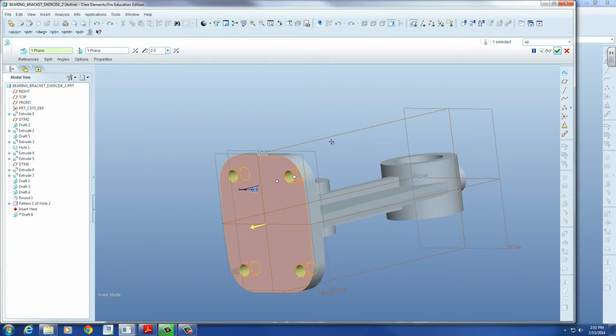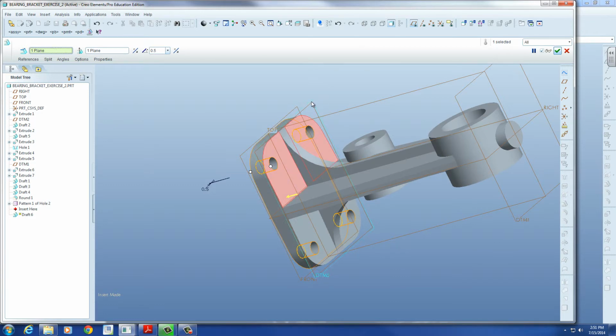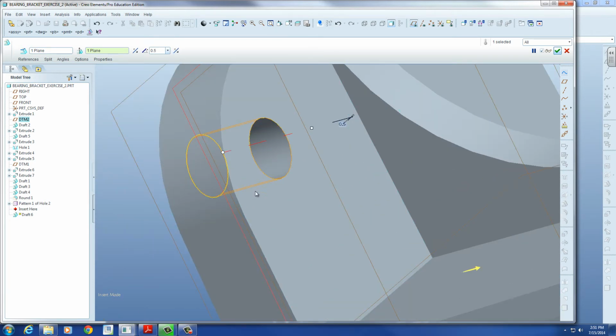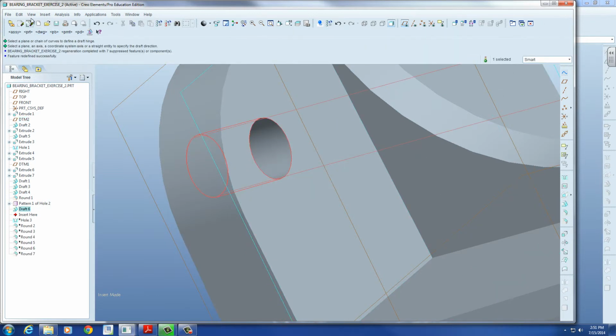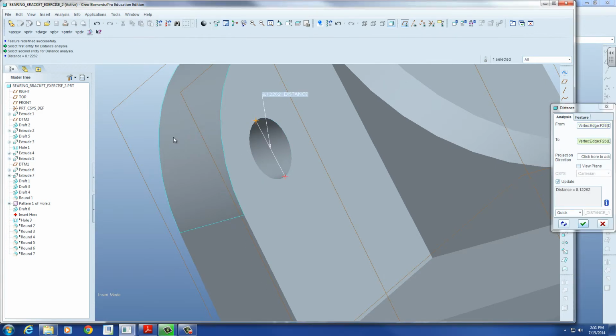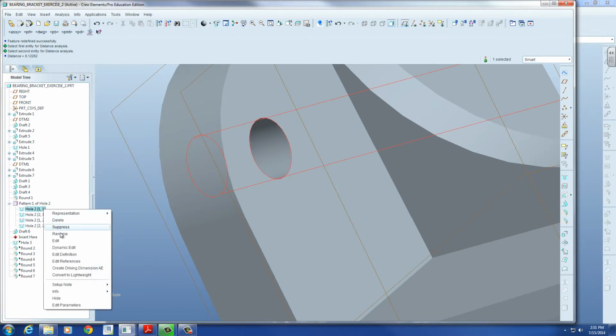Let's go back to our planes. Let's change this to back here. Oh, that's an angle plane. We can't do that. It's 8.1. If we change this back to 8, it's just getting bigger at the bottom. We just wanted this to be bigger at the top for lead-in, but we're not going to be able to have it. We just need this to be 8 because that was keeping our clearance to our hole. So let's go back and change that hole again. So we were doing the right thing in the first place.